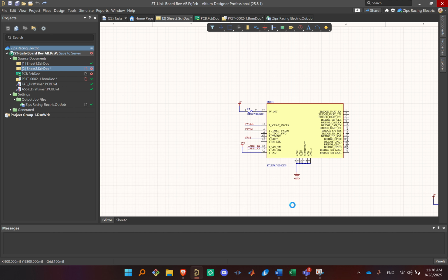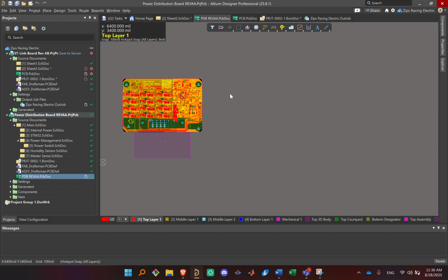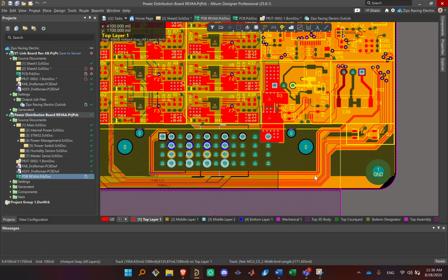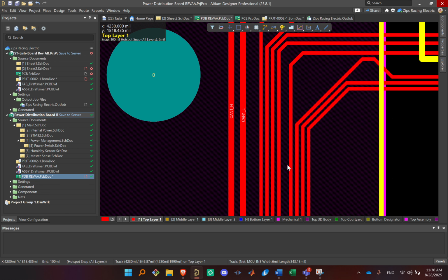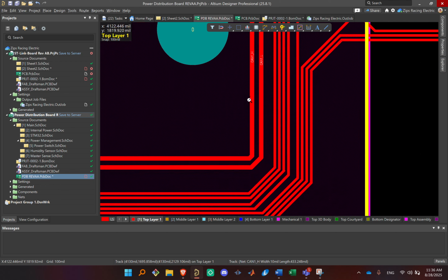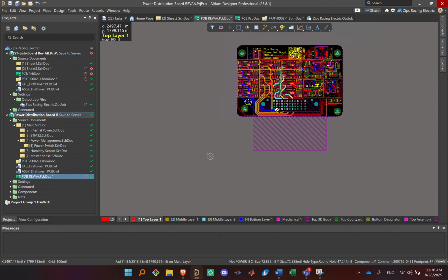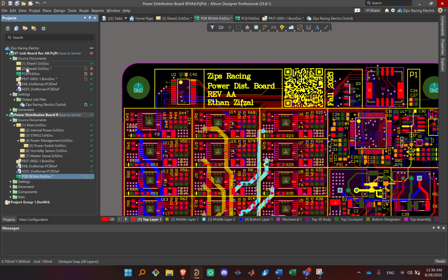If you're opening up a circuit board and you have, let's say, 10 nets all routed next to each other, and they're named like net J1, net J40, net J, whatever, it makes it extremely complicated to figure out what is going on. You can see some of that here. There's, what's that, 4, 8, 10 nets going there. And then you also have 8 other nets on other layers below it. Naming things is a very good way to keep track of what you're actually working on.